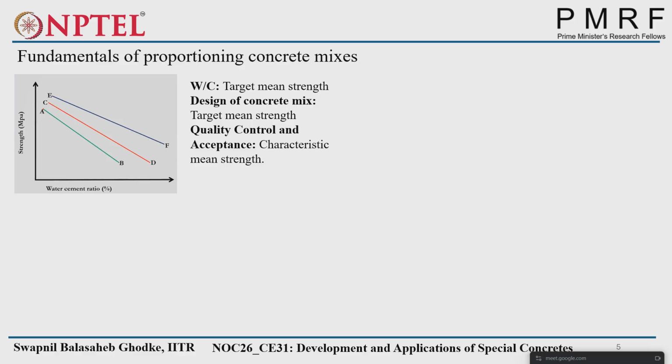Even if there is enough water, still 18 to 25% water is required to get full hydration. But we are providing an extra amount of water. Normally, 0.35 to 0.45, and sometimes almost 0.5 water cement ratio is used.